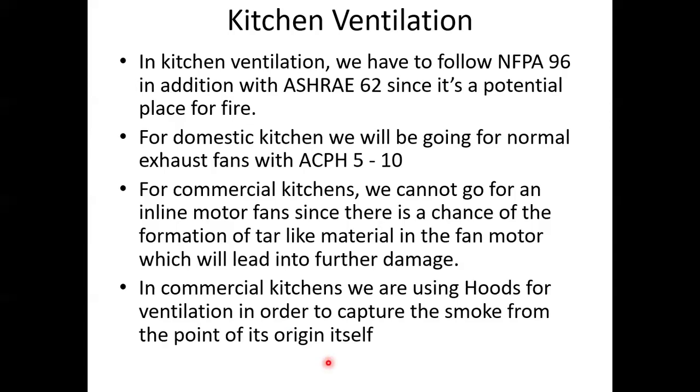So once again, there are two types of hoods available. The first one is the type 1 hood and the second is the type 2 hood. Type 1 hood implies it should be used to capture oily air. That means inside it you'll have a separate oil trap, so along with the air, you can trap the oils from the exiting air itself. The type 1 has an oil trap and is used across frying areas, barbecue areas, and even for grills. In those specialized areas, you can use this kind of type 1 hood.